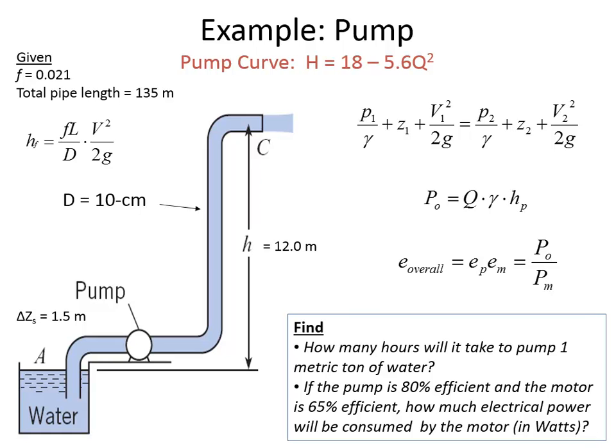Yes? So on that drawing, if you were to put a point where point 1 and point 2 are, would point 1 be right at the entrance? Good question. No. Point 1 would be right here. And the reason why I say that is, remember that we said that the pressure at 1 was 0. And the pressure of the water at the surface is the same as the pressure of the air. And so the air pressure in terms of gauge is 0. So if I wanted this to be location 1, then I would have had to actually calculate what the water pressure is there.